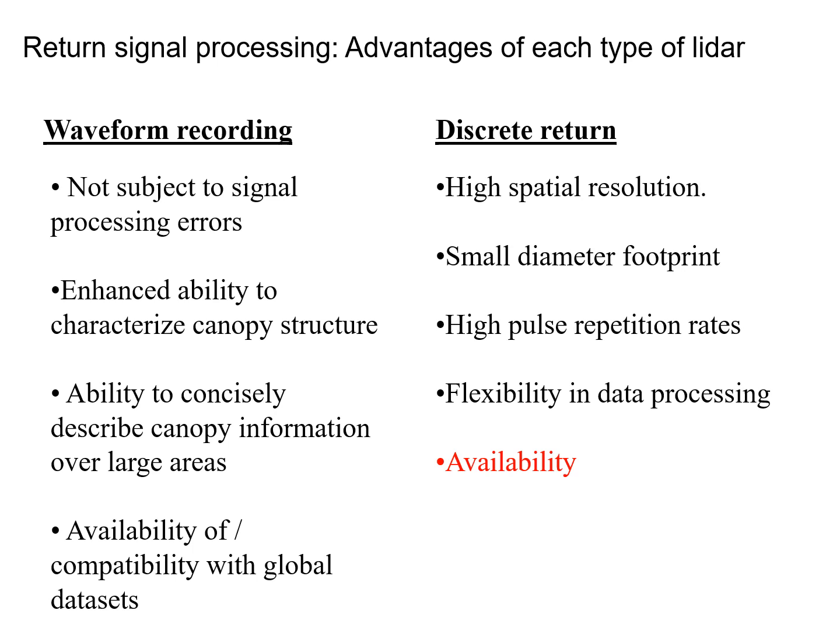Very often you don't want the number of points you're going to get per meter squared, because these days they fly with crazy numbers like 12 points per meter squared, and that's just a lot of information to process. Very large files, you know, file sizes at around 100 gigabytes or 500 gigabytes.